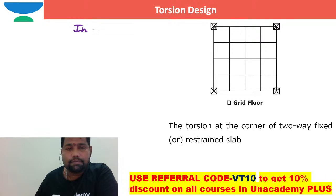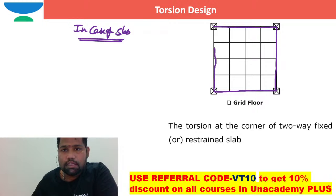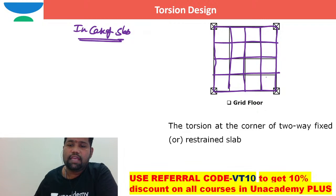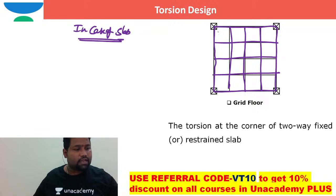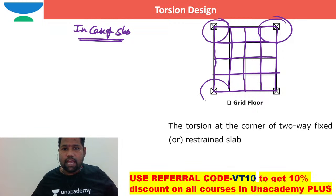In case of a two-way fixed slab, if the beams are running in all four directions in this way, 1, 2, 3, 4, especially if you take the corner slabs, torsion is developed at this slab, at this slab, at this slab.